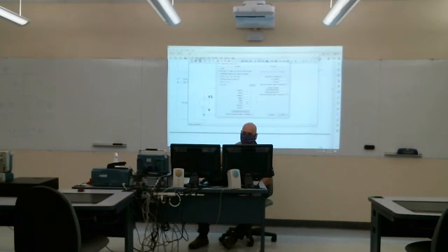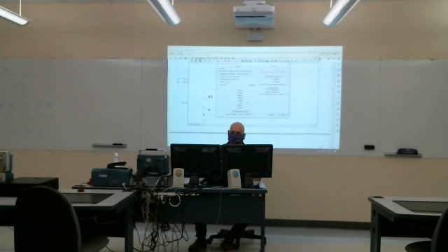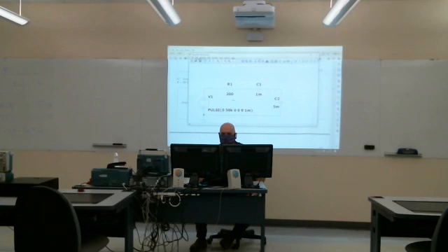If I'm going to make this thing 1 millisecond in duration, I have to give it an amplitude of 50,000, right? 50,000 times 1 millisecond would have the same area. So 50K here. Delay of 0. I don't know if I need all of this. 0, 0. It's not periodic. Never really quite sure, so we just run the analysis and then I'll take a look and see if it looks right.